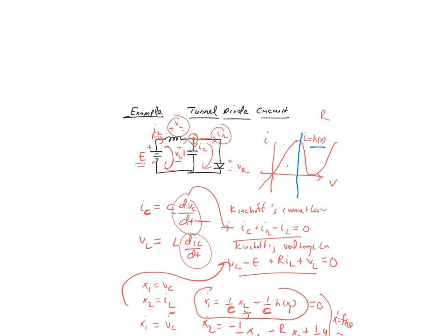There is no derivation involved here as such. It's saying that I have a diode. They might have done lots of experiments to get this h of v, or whatever the circuit is. So okay, that's the component that you bought, and they say, you apply this much input, this is the voltage, this much current. Basically, they give you a curve. If your current is this much, your voltage is this; or opposite, if your voltage is this much, this is the current. So this is the characteristic of the tunnel diode that you have put in here.